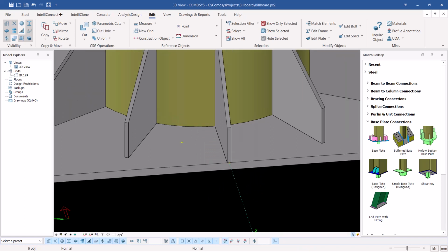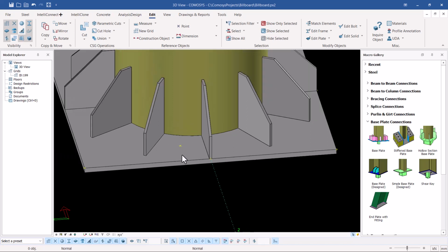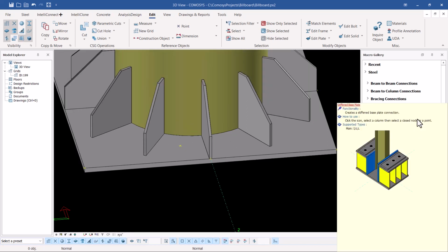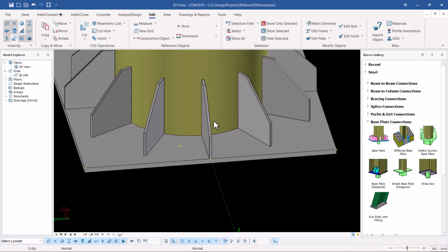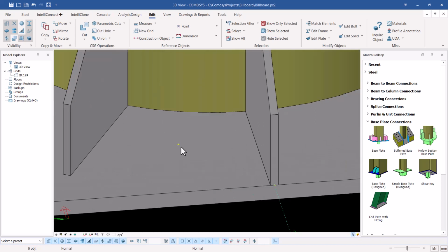Since we have the midpoint here, we want to create holes all around, so that we come now with anchor bolts and place them right there. The rules in creating holes here: we need some extra points that will help us in creating the holes. The hole will be used for anchor bolts of M20, or a diameter of 20, so the hole should be approximately 22 millimeter.